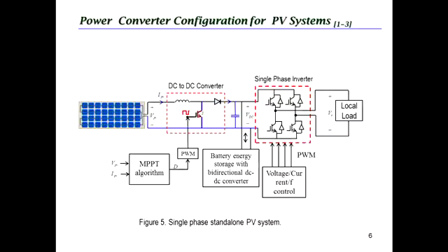If we don't have a battery, then we don't convert. There are mechanisms here, parallel diodes and so on, which will mean that not all the available energy is being extracted from the PV array. Only the amount that can meet the local demand will be converted into AC supply for the load. So this is a typical PV energy converter system compared to what we saw in the previous few slides for wind power generation systems.